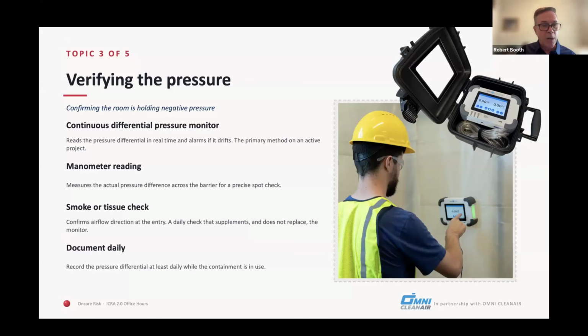Problems I've seen with that, Josh, Olivia, is that they put the tube in some space, it goes into the anteroom only. And so you're measuring differential pressure between the outside area versus the inside and getting that pressure change in these devices, such as the Omni device and others. And basically it just says, here's where it's at. Sometimes that tube gets clogged up. Sometimes it doesn't get put in the right position. So you want to monitor that. And back to your point, Josh, we do that in the hospitals as well. We calibrate these devices on an annual basis.